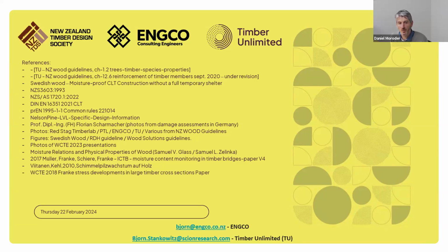It's perhaps worth mentioning a little bit on the end grain and moisture. I think the easiest way for the water to get into the timber is from the end grain. If you look at a tree, this is how the tree works: it drives the water up the trunk to grow the leaves. That's the same for your member. Any water will always enter a member from the end more easily than from the surface. Obviously, over time, it will also migrate through the sides, but the worst points are the end grains.